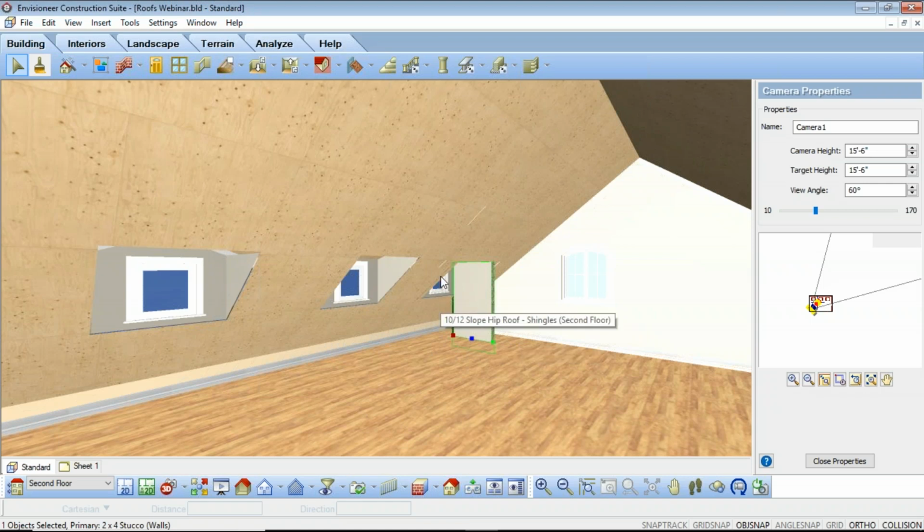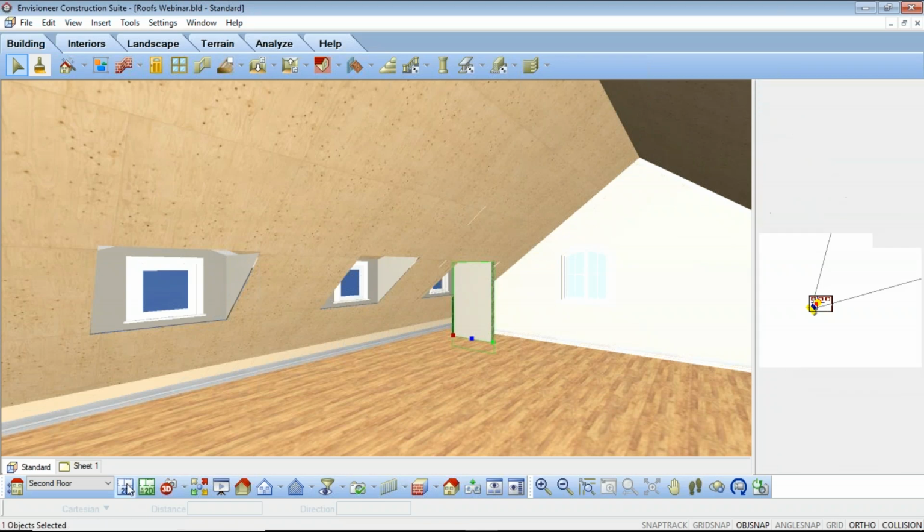And then you could add in your walls that run underneath to create your knee wall, and then fill in the spaces where you need to. So if you want to add in another wall here, you could do that to create that alcove look of your dormer area. But that question we get quite frequently. And again, the wall will always, if it's turned on, extrude to the roof, top and bottom. So if you do want that to be flush, just turn that level option on and then adjust the height as needed. I'm going to go back into 2D.